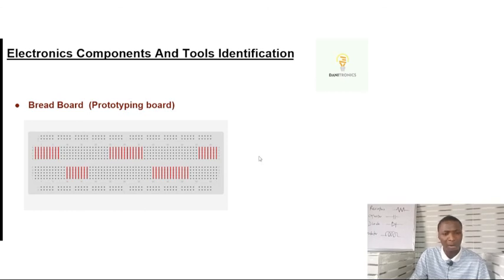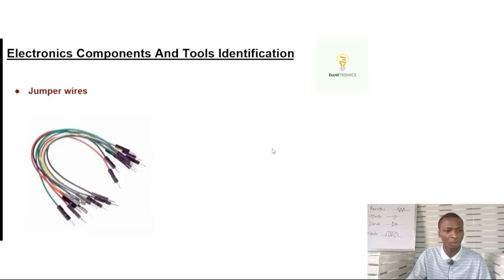So that's just how a breadboard works, because upon this breadboard we are going to build our electric circuits. When I give you a circuit, or when we want to design a circuit, it is on the breadboard we design, after which we can now transfer to a printed circuit board.